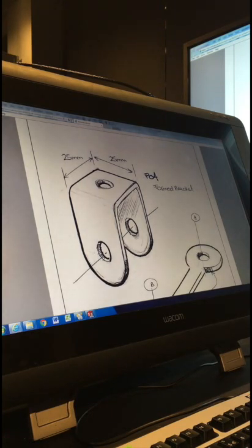We could also, instead of from the right side, we could start from the left side. So this shape that we see here, which is like a semicircle on the bottom and some straight lines across the top. We could take that, we could extrude across all the way, and then we could cut through the middle. All right, that's another option. And then another option again, start on the top, draw that square, extrude straight down. We could cut off then a bit across the bottom, cut that hole, again, cut this middle side out. There's probably another 5 or 6 different ways that you could model the same part.